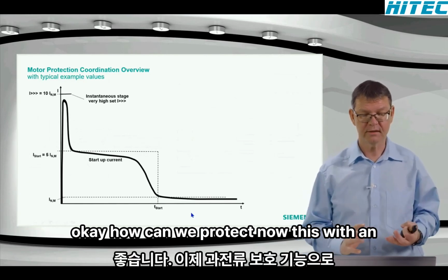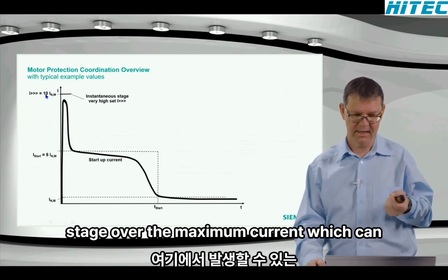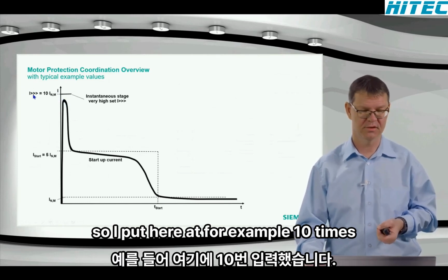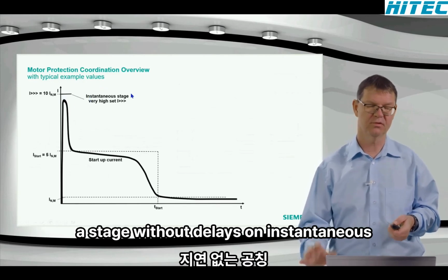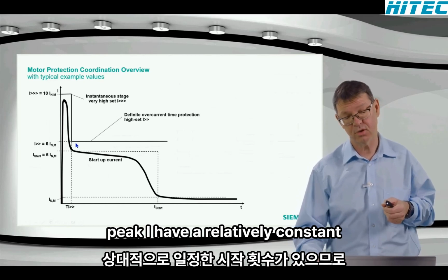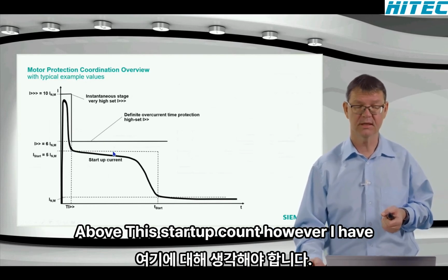Okay, how can we protect this now with an overcurrent protection function? First idea is to put an instantaneous stage over the maximum current which can occur here under normal conditions. So I put here, for example, 10 times nominal current, a stage without delay, so an instantaneous stage. Then I can go behind and say, okay, after this peak, I have a relatively constant starting current.